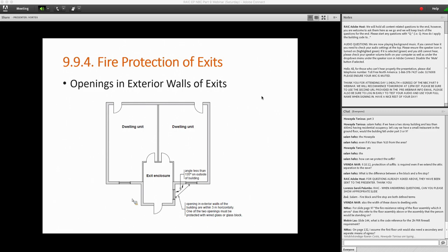Could you give an example of an occupancy in a corridor? So sorry, I had to pause on that for a second. So an occupancy in a corridor could be, for instance, a lounge within the corridor, or where you have a vestibule, or just a typical occupancy within the corridor, and you still require to maintain the required width of the path of travel through that corridor, which is 1100 millimeters.